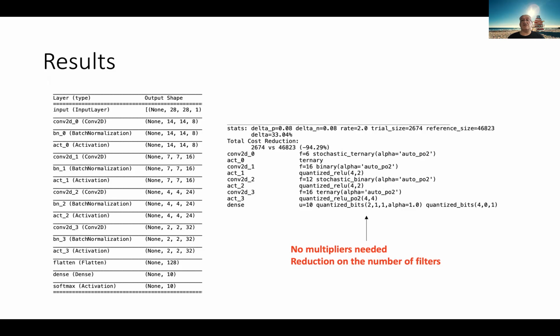A word of caution here is that our method for estimation of power or energy is completely architecture agnostic. We consider the estimation of the operations execution. We consider the estimation of bringing the first data from the SRAM to the PE for the execution, but we don't consider, for example, that sometimes you use some internal caching, because that would depend on the architecture.